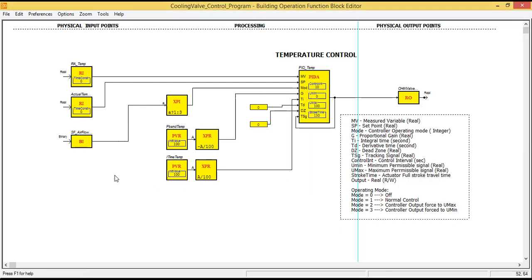So I'm checking if there is airflow, meaning the air handling unit is working and airflow is sensed across the fan, meaning the fan is delivering air. It will be fed to this expression block. Now what is this expression here? If A, then 1, else 3. So if this airflow is 1 or true, then the output of this will be 1.